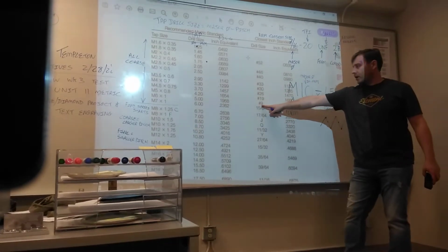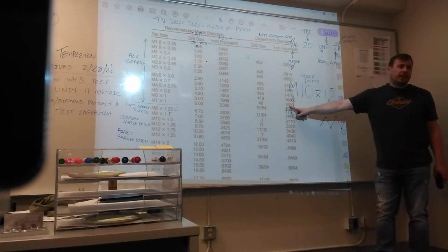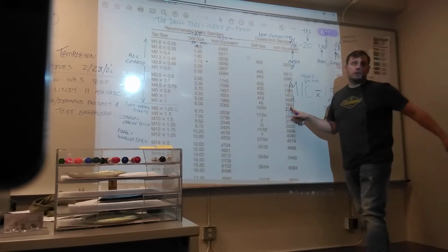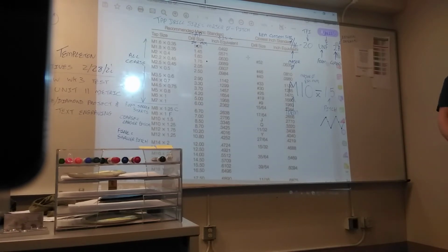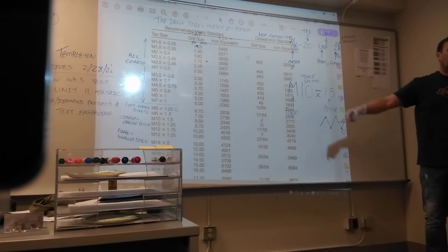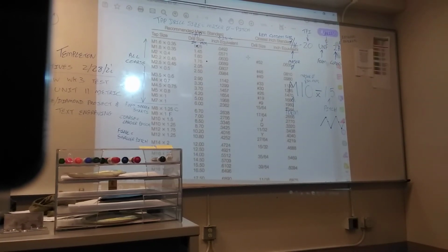So the number 9 drill is 196 thousandths. How much difference is that? 8 tenths. Virtually no difference. So the guy will just say, use that inch tool and we'll buy the tap. That means they can save some money and make a little bit more profit.